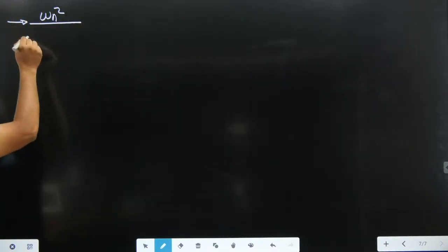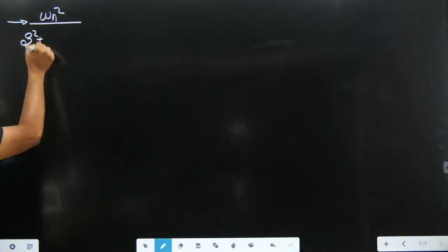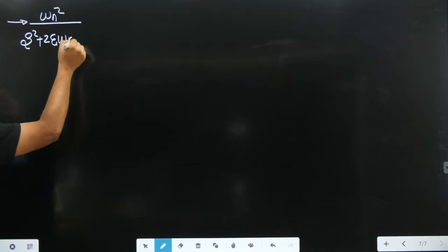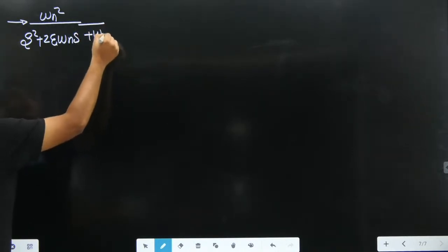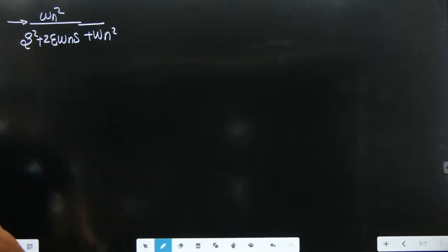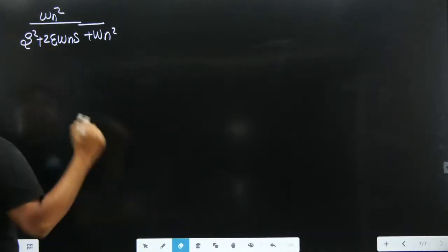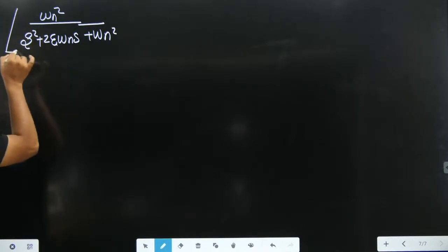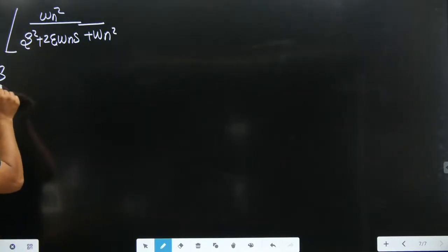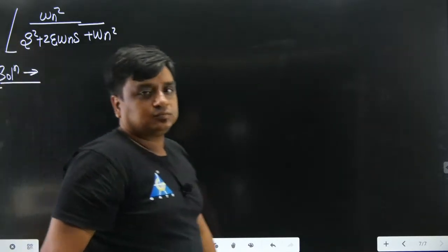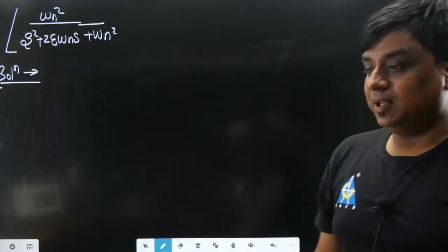Let me focus on the standard second order system, which is k times omega n square over s square plus 2 zeta omega n s plus omega n square. Forget about the k, because if k is positive, no angle is introduced by that positive k. If I would like to know how much angle would be offered by this system, may I know what would be your answer?